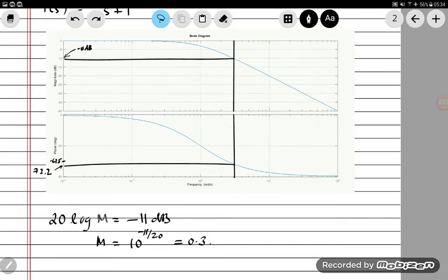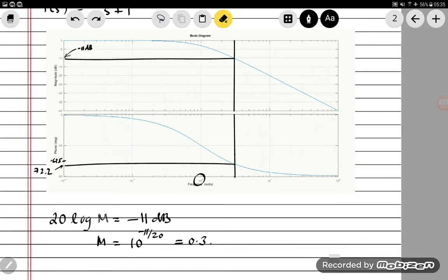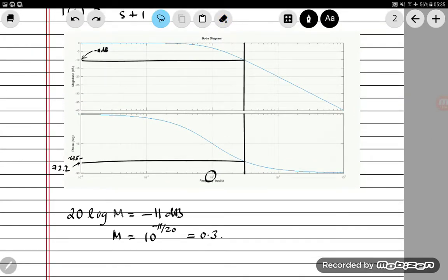As I've said in class, there are some other useful things we can read off from this Bode plot. We can see that for low frequencies, let's say lower than 1 radian per second, the amplification factor is a constant, and that's 0 decibel, which translates into 1 for our amplification factor.